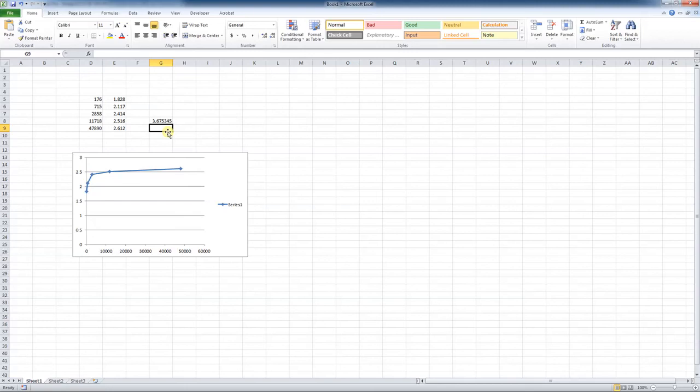You would have to look at your problem very carefully, make sure that it was physically meaningful in engineering to get a 1% error on something. But it's possible. So we could use the 47,000 element mesh if it was justified. But even in that case, I would use an optimized mesh. There's way too many elements in there.